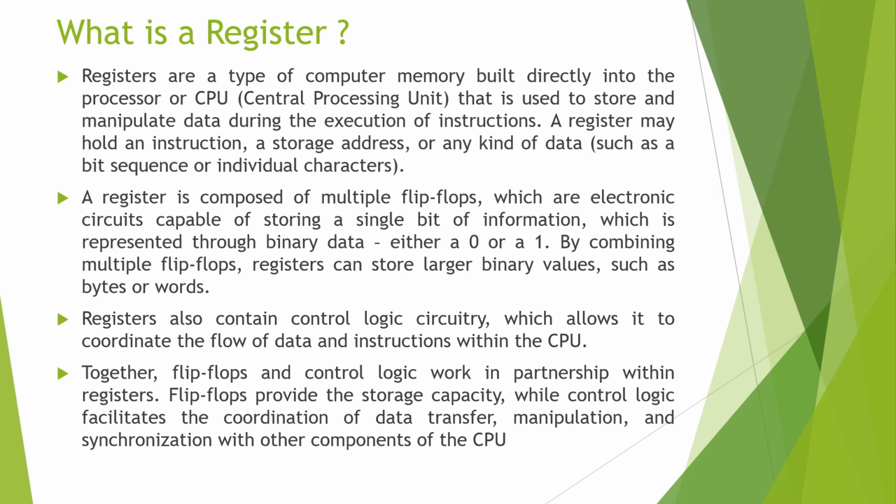For example, whatever the bit size of a microprocessor, the registers inside it have the same length. 8085 is an 8-bit processor, so its register length is 8 bits, while 8086 is a 16-bit processor, so all registers inside the 8086 are 16-bit registers. 386, 486 and Pentium, that is 80586, all have 32-bit registers. So the register length inside these microprocessors is 32 bits.